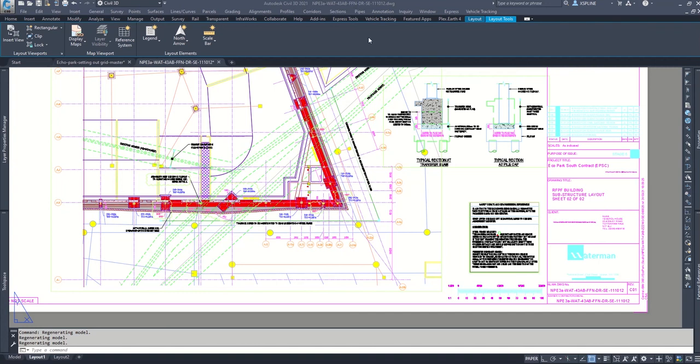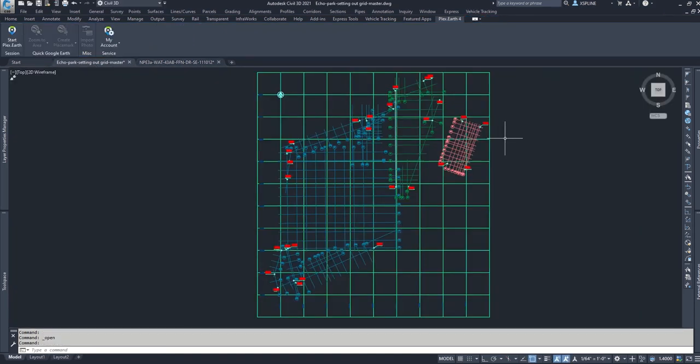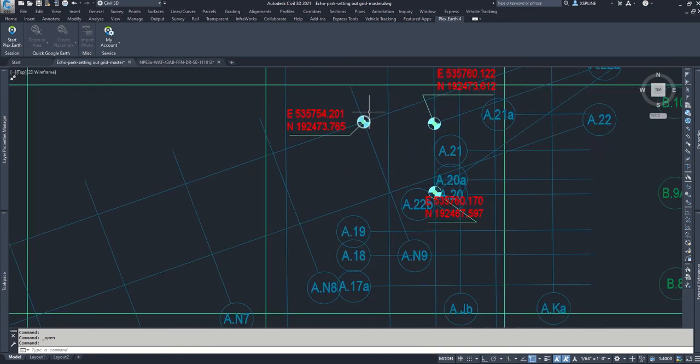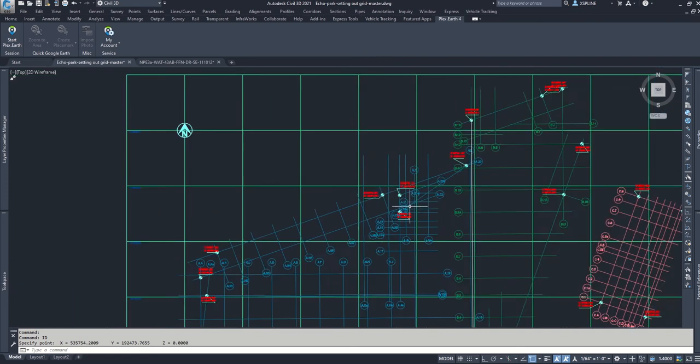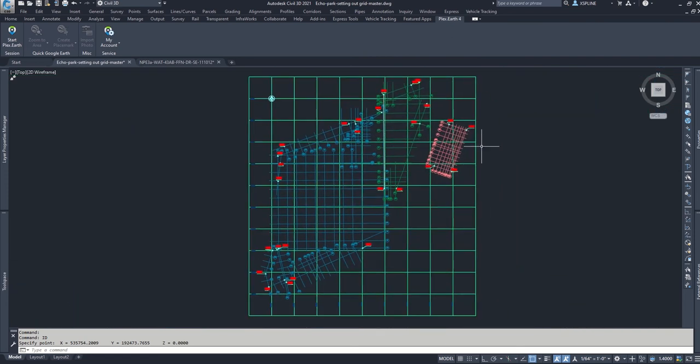Hi, I'm going to do an example of how to align a drawing to a coordinated model space if it's not on a coordinate system. So I have a drawing here, a reference file, which is on a coordinated space, and we can check that by IDing one of the coordinates, typing ID, and you can see that the readout down here corresponds to the coordinate.